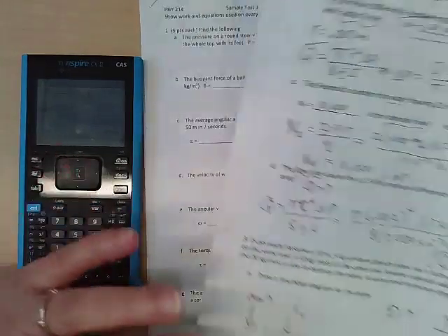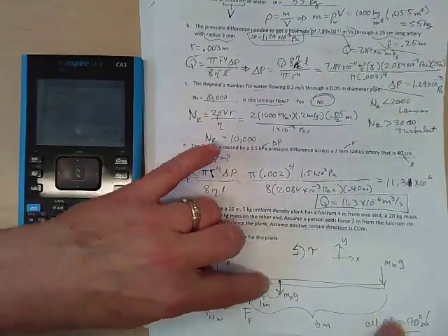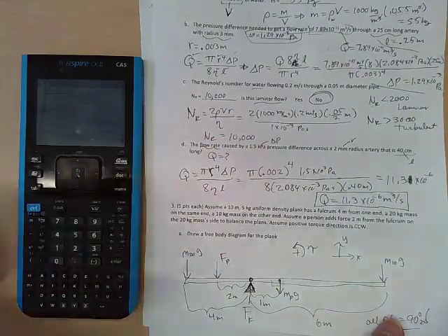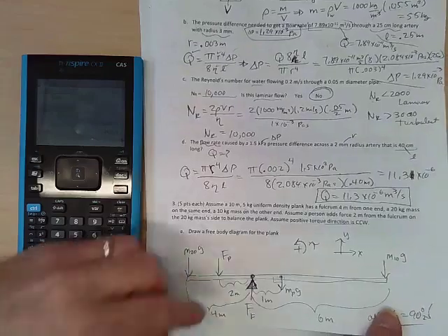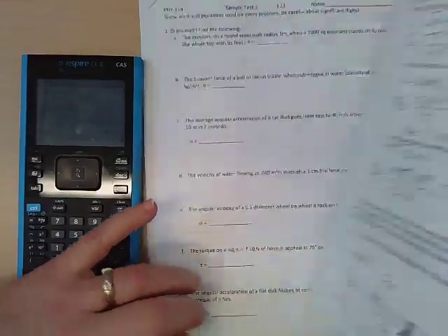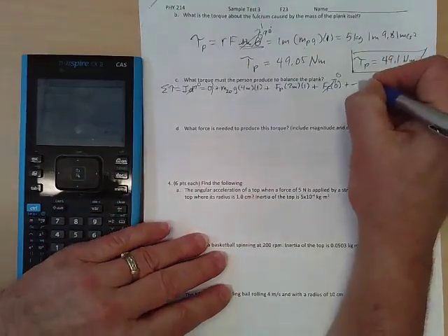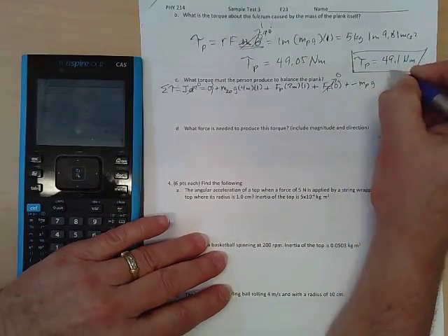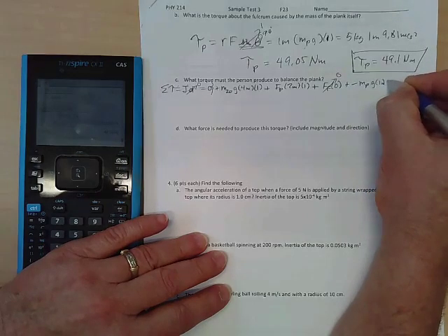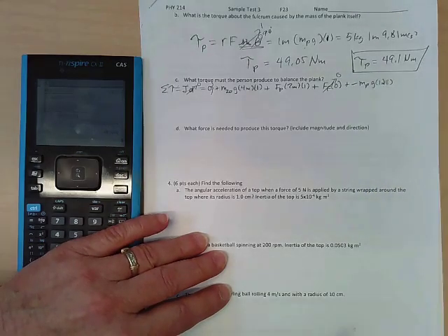Right? Going to the next one, we've got the mass of the plank itself, and it's 1 meter away from the fulcrum, but it's causing a torque clockwise, so it needs a negative sign on it. Right? So it's going to be negative mass of the plank times g times its moment arm of 1 meter, and then the sine 90 is also just 1.